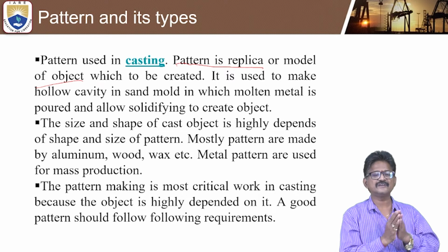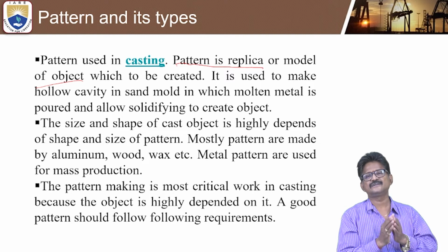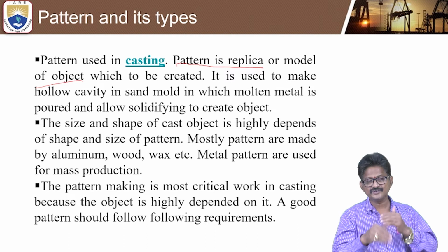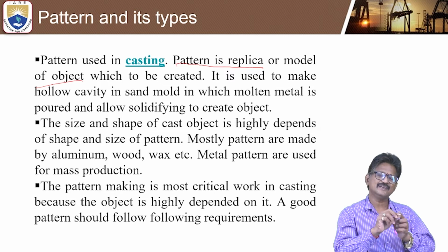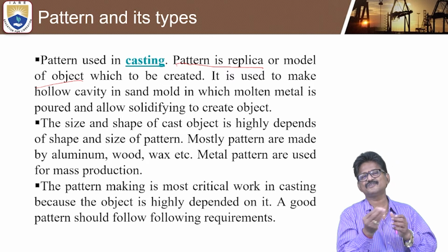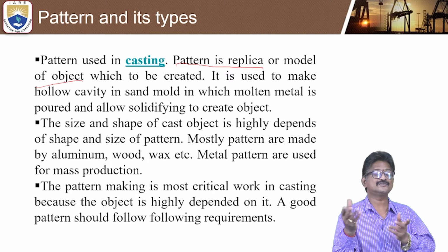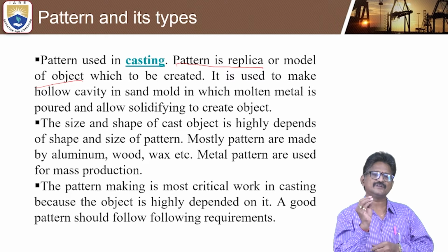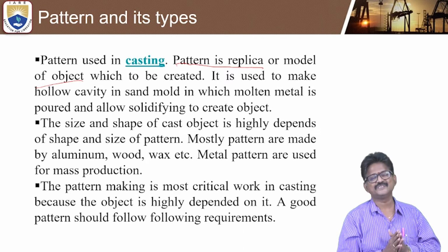For example, when you want to produce a limited number, like 100 or 200, you can use the wooden pattern. If you use it for so many, 1,000 or more, the wood pattern will have extra parts that all get removed, and some problems may occur. The final component may also be defective. So only when you want a small number of products, you can use the wooden pattern.